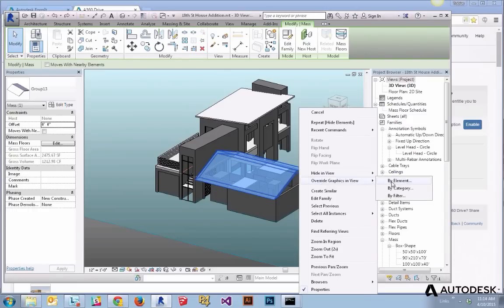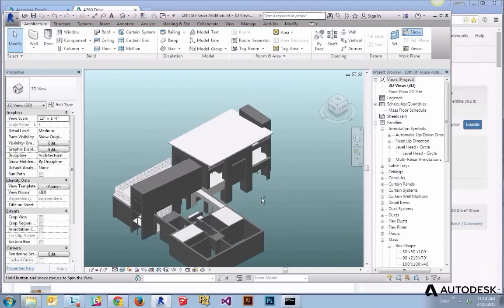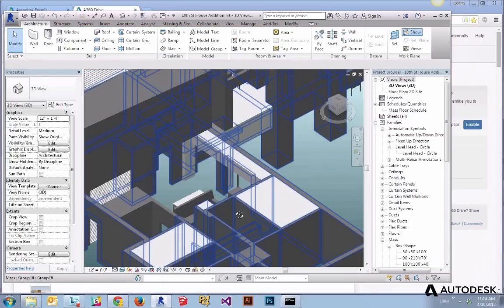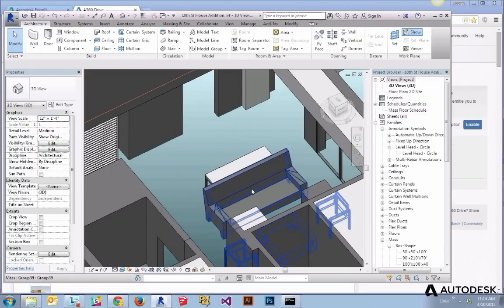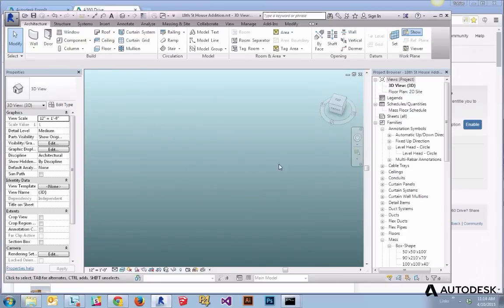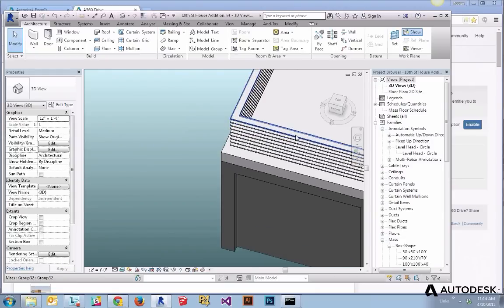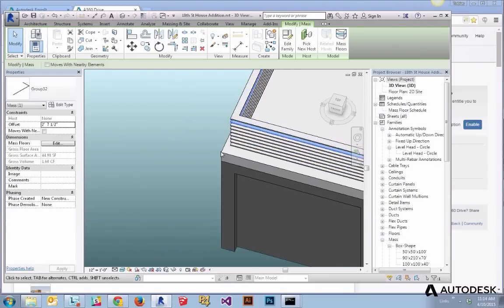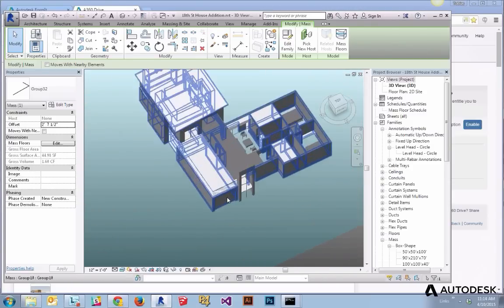And you can look inside it and see that even those little furniture pieces that I made all translate over from FormIt into Revit. And those louvers all translate, and these railings translate also. And the cool thing is that these are now families in Revit. So they're mass families, and I can continue to tweak this geometry after I come over to Revit.